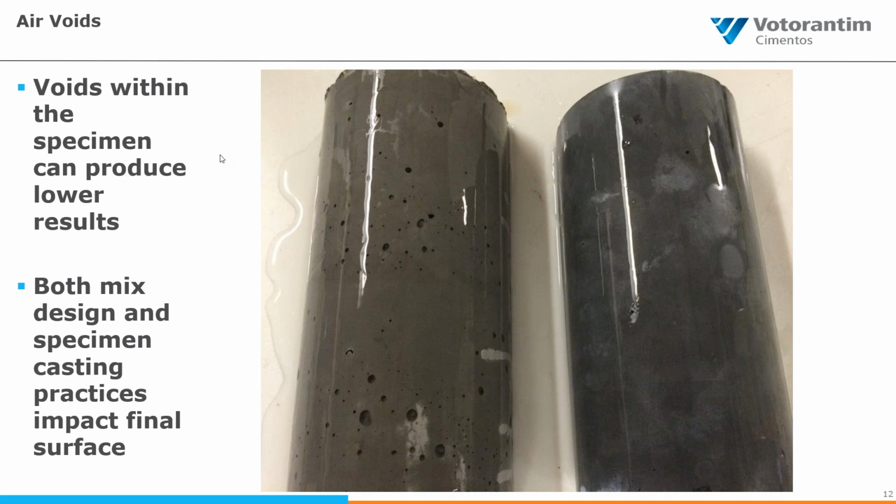So we would specify, depending on whether they were puddling with the mix or they were pouring major forms, a tighter flow spec, and then generally a higher flow spec. The most comfortable level and the most consistent level we found was between 24 and 27 inch spread. So that's generally where we spec the placements flow for these types of mixes.